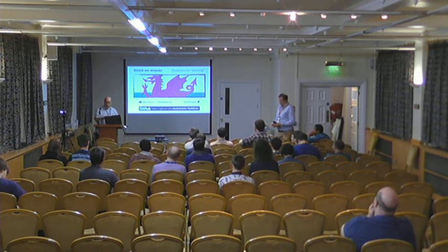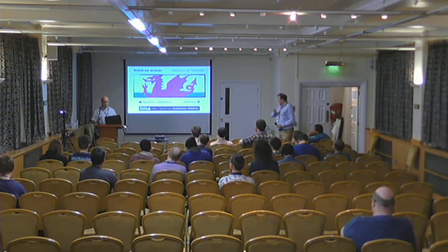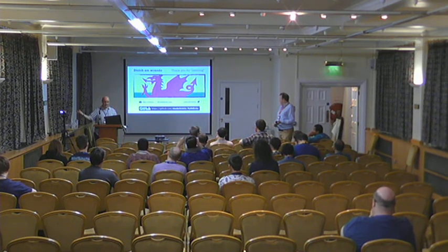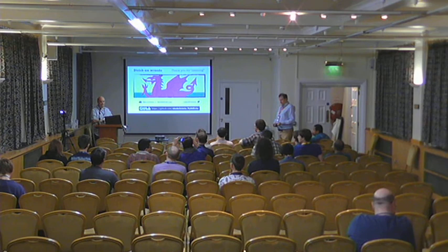So you can do digital filtering, but you can't do that in the interrupt service routine, because in the interrupt service routine you've got very limited time in Python, and also you can't use floating point precision. So any algorithm you want, you have to run outside of the interrupt service routine. And the board doesn't have an awful lot of math libraries built in. So unfortunately, that level of digital filtering is sort of out of bounds for this hardware.